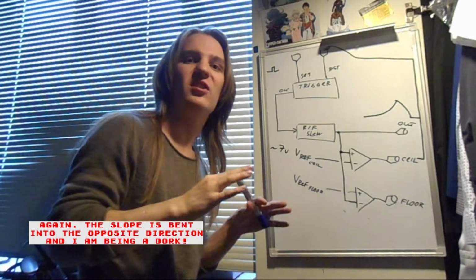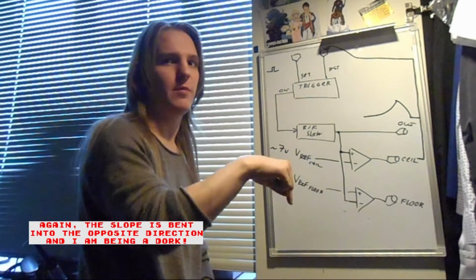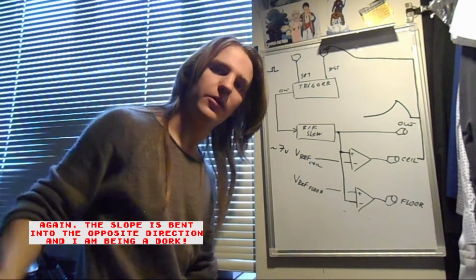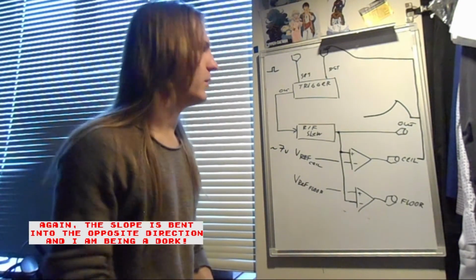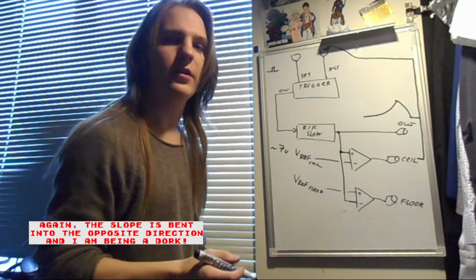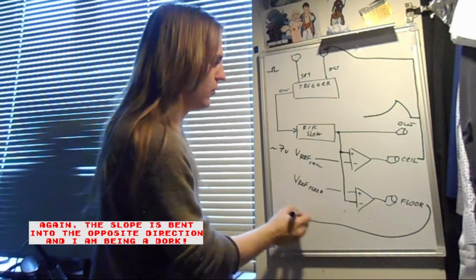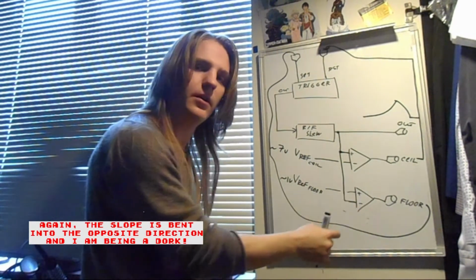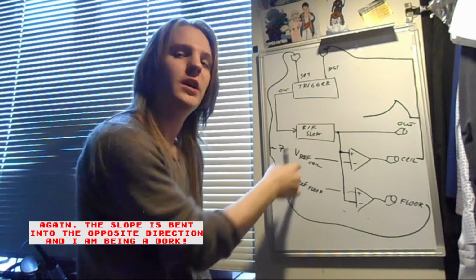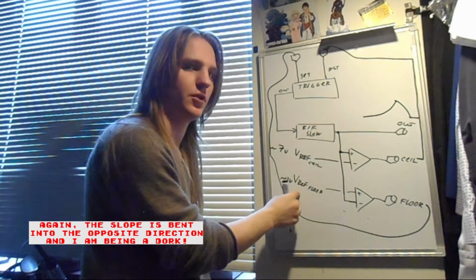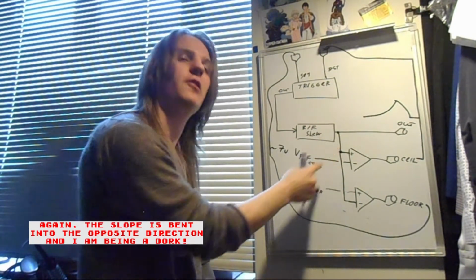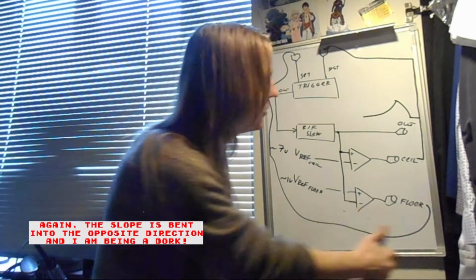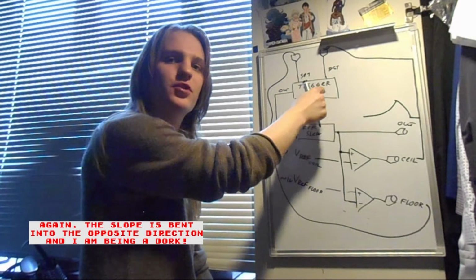Imagine if we had some kind of a key or a button, so when we tap it into the set, it starts going up and then automatically drops down. An attack release envelope. We can make it even better and patch the floor output into the set input. This comparator compares if the output of the function is lower than this voltage reference floor. So if this thing is lower than, say, 1 volt, this thing gives us 8 volts, logical 1.